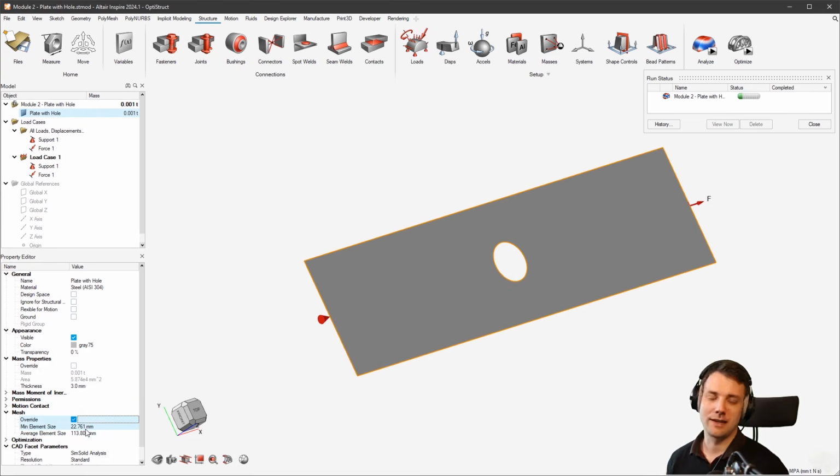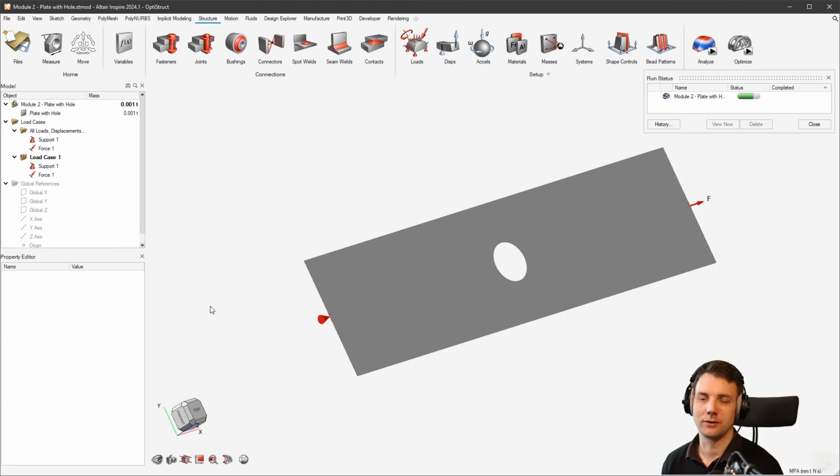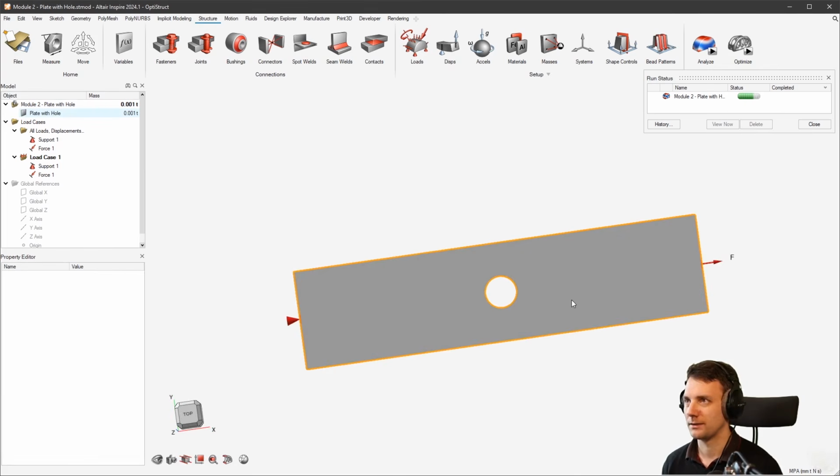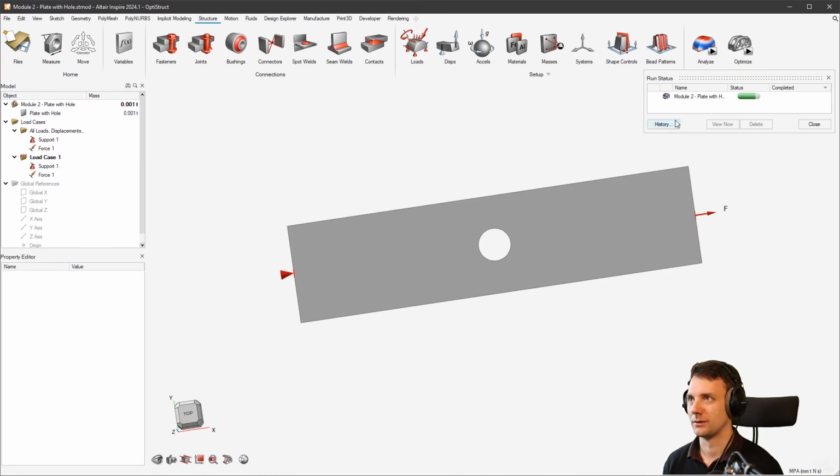Those two things are constrained together. You cannot set them equal, because I think there should be a ratio, I think 1 to 5 or so. The solver will complain if you set them wrong, but just as a rule of thumb, take your average size, let's say, for example, 3 millimeters. And then your minimum element size, for example, 0.2 times 3. So let's go with 0.5, for example. This should work. We can check that in a bit, but it will take a little while to run.